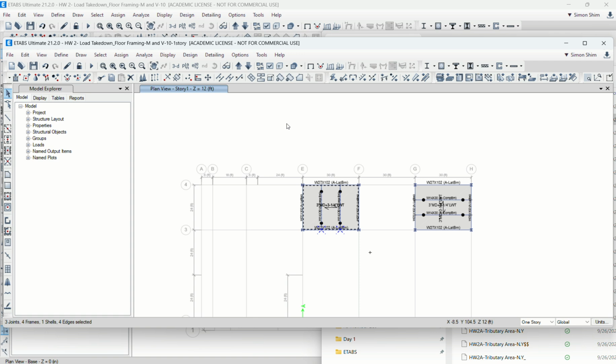Since we know this line load, let's say 1.2 dead load plus 1.6 live load, which is 1.2 times 450 plus 1.6 times 1,000. So we can calculate the total ultimate line load, dead plus live load. This is the ultimate load. Now what do we need?